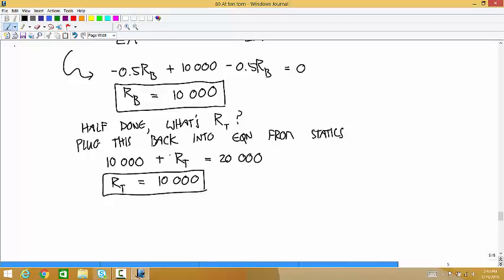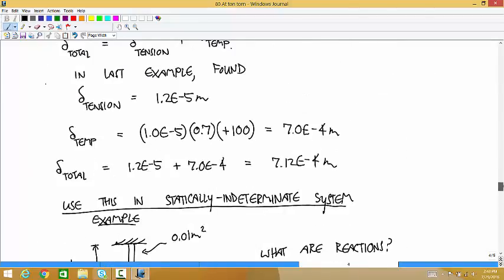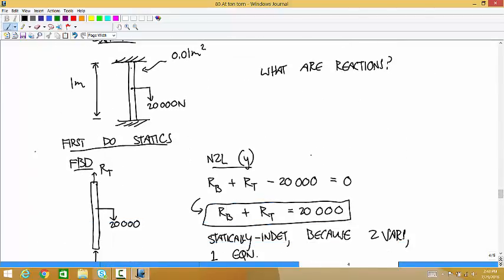So there was a pin and there was a rigid connection on the bottom. So that is basically this example. Yeah, it was two rigid attachments, but if there was a pin up there, it would have been the same thing. I skipped x components and y components for things just because there was only stuff going on in one direction. Yeah, that's exactly right. If you really treated it carefully like a fixed joint, you would have put in the couple and all the rest, and then at the end it would have just been a lot of zeros and we would have been left with this.